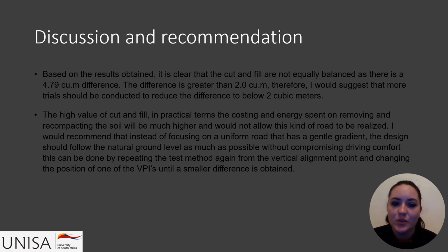Okay, based on the results obtained, it's clear that the cut and fill do balance, or almost balance, as there's a 4.79 difference in cubic meters. It would have been better to have it under 2, but this is still within range.